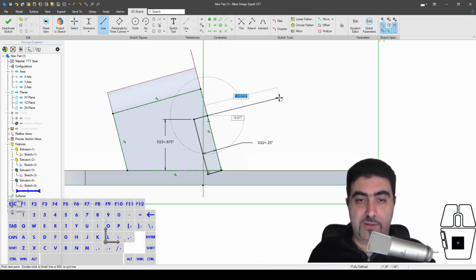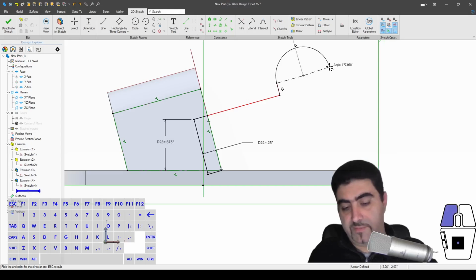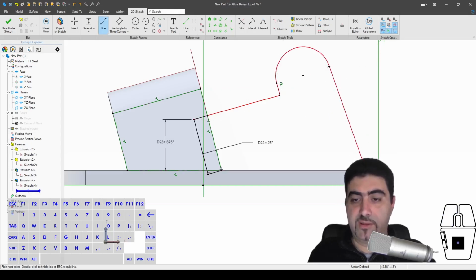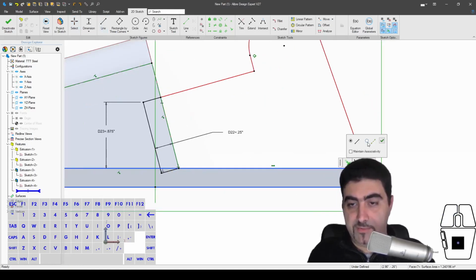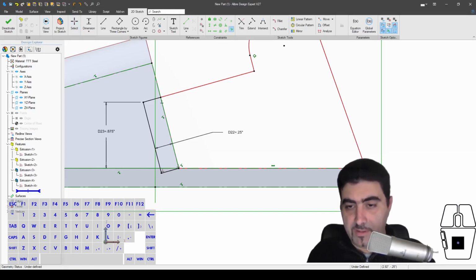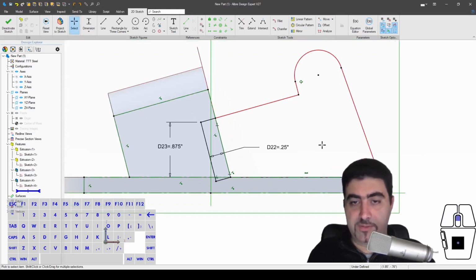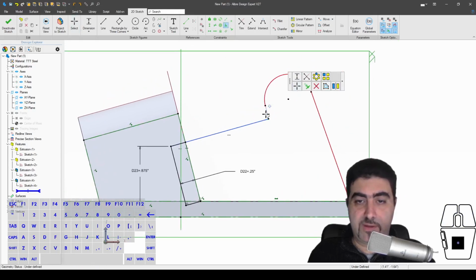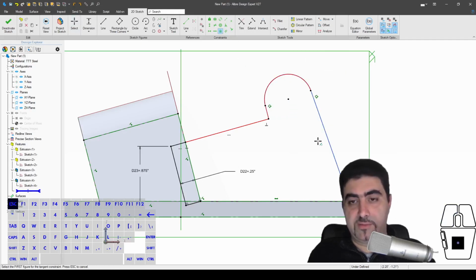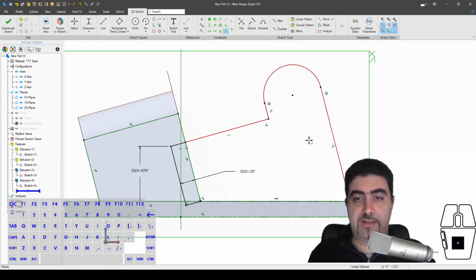But now let's go and sketch everything. You know, do the rough sketching of everything. So we've got those lines and a tangent arc, and then we close it off. Okay, let me project this in. So this line stops there. This and this is collinear, and we've got a perpendicular constraint going there, and then I'll just do tangent here. Is that enough? No, I also need to do a parallel between the two.